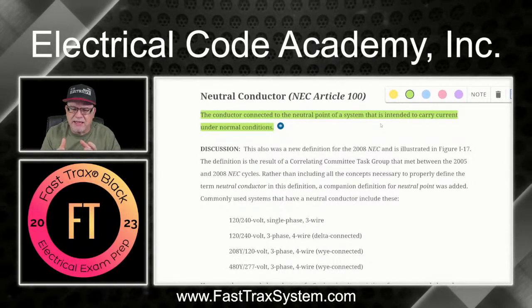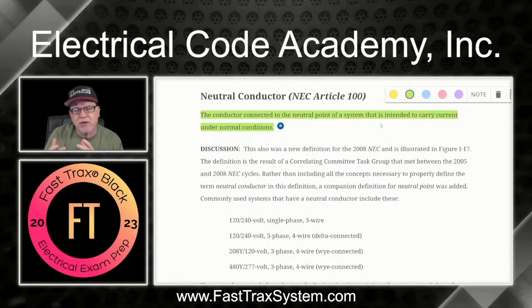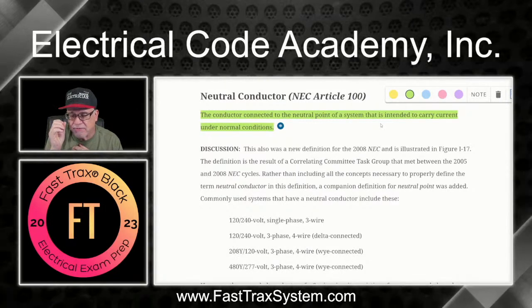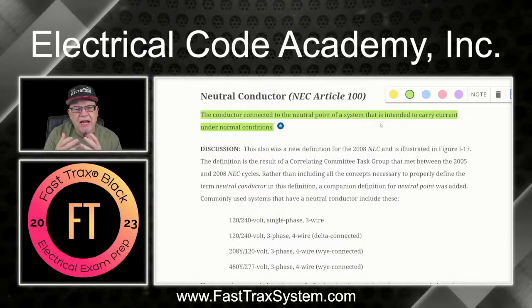In other words, when you install it and you hook everything up, you know that at any given point it could carry current. Now, typically when we work with systems in the NEC, the neutral conductor is sized to handle the maximum unbalanced load. And we'll talk about that in 220.61 when it comes to a calculation of the neutral conductor, especially for things like feeders and services. But it's really important to understand that the neutral conductor is designed to carry current at all times under a normal condition.